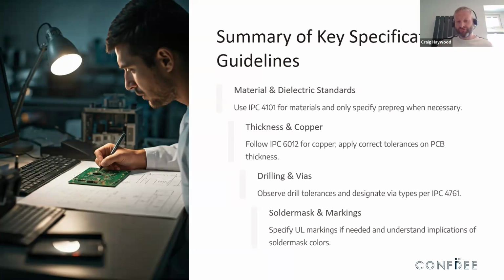If too much goes onto the drawing, it can sometimes become overcomplicated with too much specified, and we're trying to keep it nice and tidy, nice and clear, so everything is just readable and easy to understand. Following the IPC standards is key for material types, for design, for filling, and also for manufacturing and release. Manufacturers will work to IPC standards as much as possible, and they will hopefully give us boards that are perfectly within capability and meet the data that you have supplied.